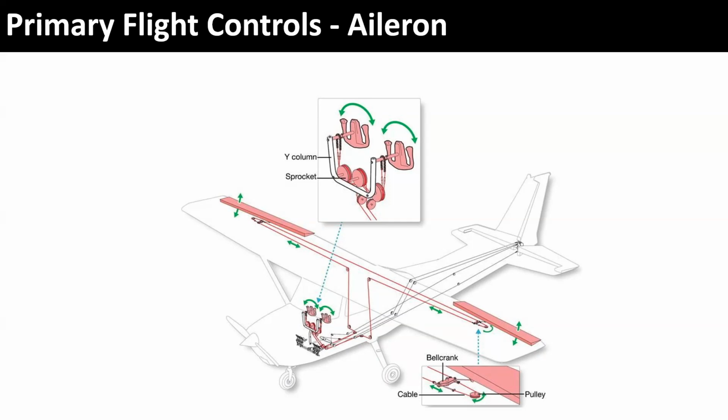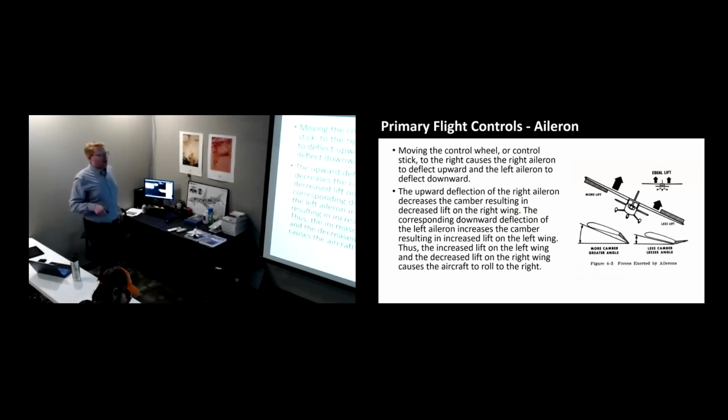Same with pitch. Anyway, when they move, there's going to be a series of cranks and sprockets and cables that move your left-right input through cables. You can see here they are coming from the control wheel back towards the pilot, up and then out towards the aileron that causes the surface to move. This is what allows the aileron to move. It's just cables from one spot to the other. Does that make sense? Okay, cool. Okay, ailerons.